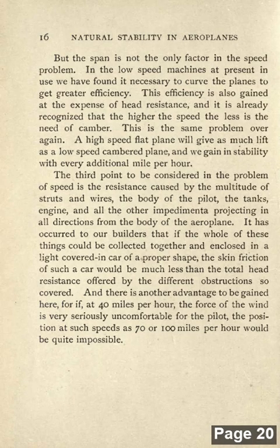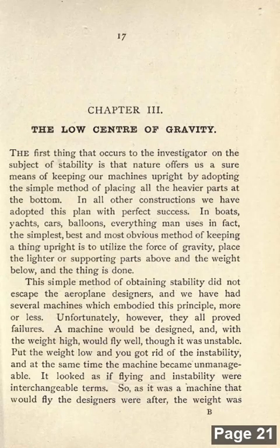The third point considered in the problem of speed is the resistance caused by the multitude of struts and wires, the body of the pilot, the tanks, engine, and all the other impedimenta, projecting in all directions from the body of the aeroplane. It has occurred to our builders that if the whole of these things could be collected together and enclosed in a light covering of a proper shape, the skin friction of such a car would be much less than the total head resistance offered by the different obstructions so covered. There is another advantage gained here, for if, at 40 miles per hour, the force of the wind is very seriously uncomfortable for the pilot, the position at such speeds as 70 or 100 miles per hour would be quite impossible.